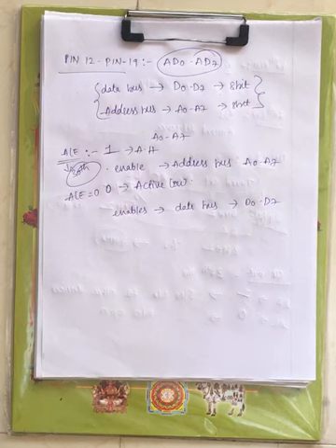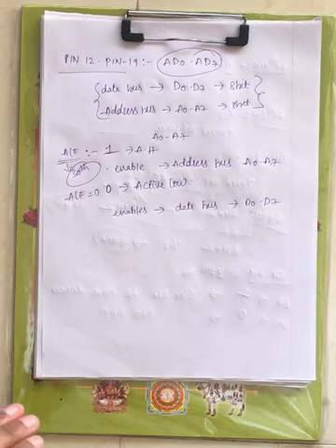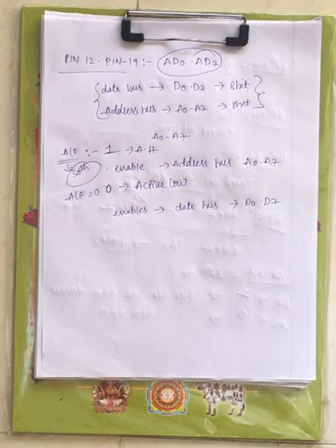Now this particular set of lines can carry lower order address and also data bits, but at a time it can't carry them together. It has to carry individually: either the lower order address or the 8-bit data.